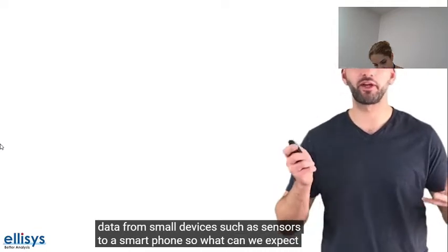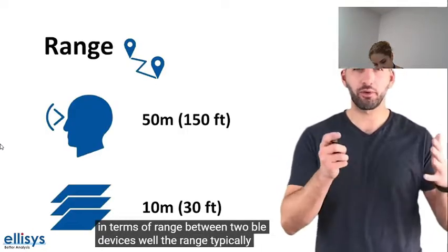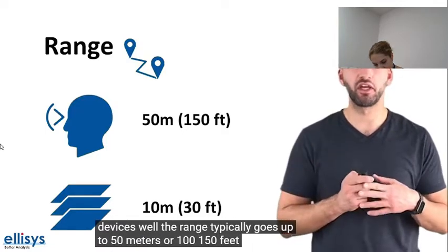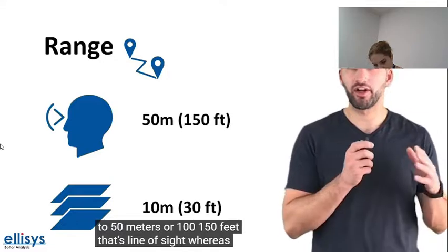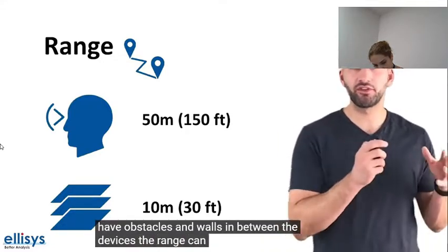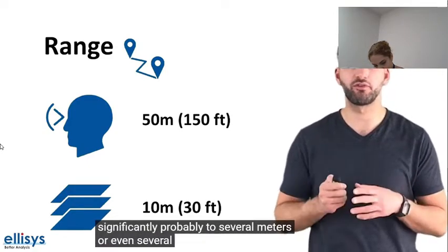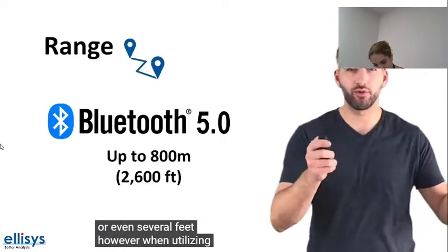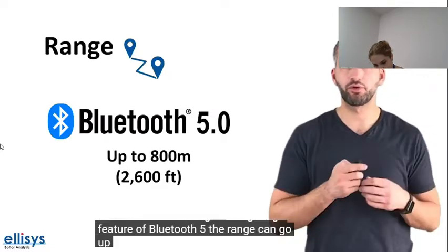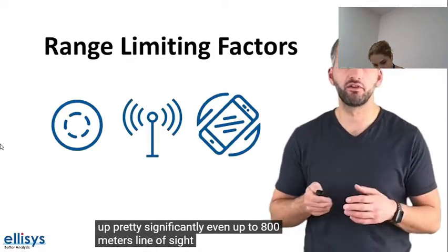So what can we expect in terms of range between two BLE devices? Well, the range typically goes up to 50 meters or about 150 feet. That's line of sight. Whereas when you have obstacles and walls in between the devices, the range can go down significantly, probably to several meters or even several feet. However, when utilizing the long range feature of Bluetooth 5, the range can go up pretty significantly, even up to 800 meters line of sight.